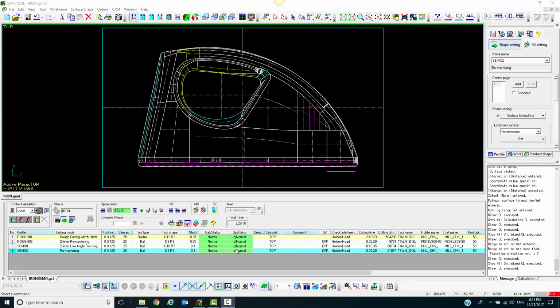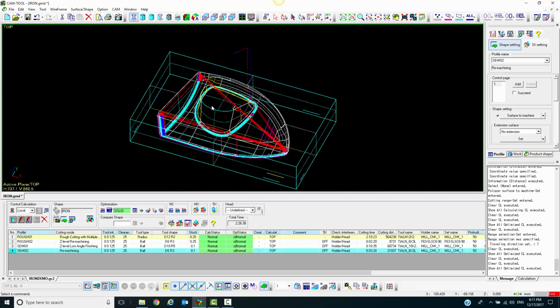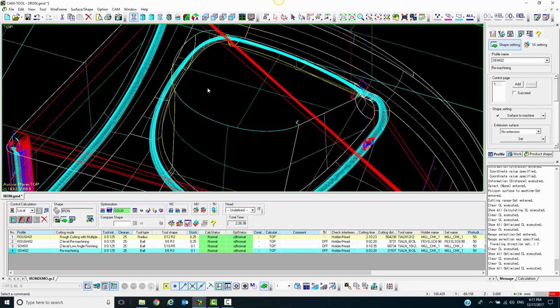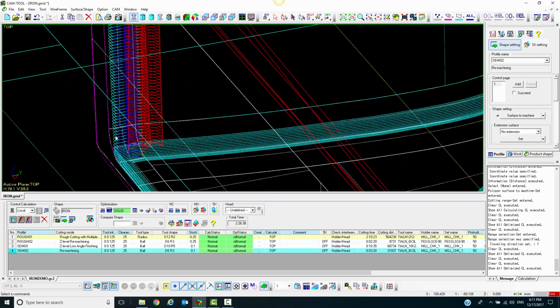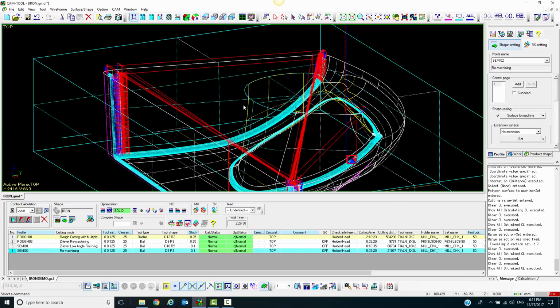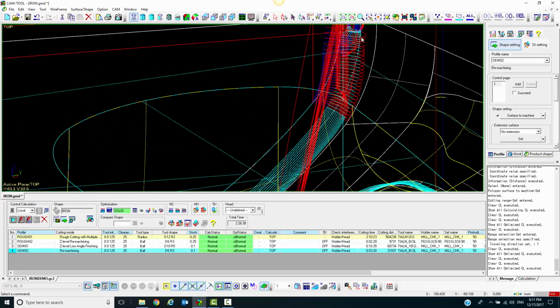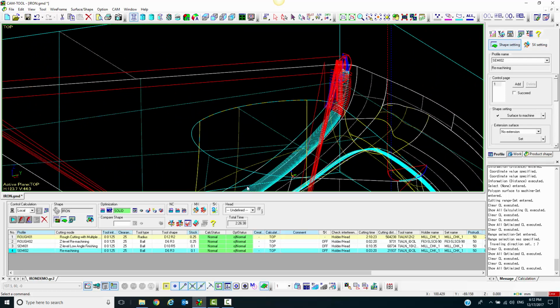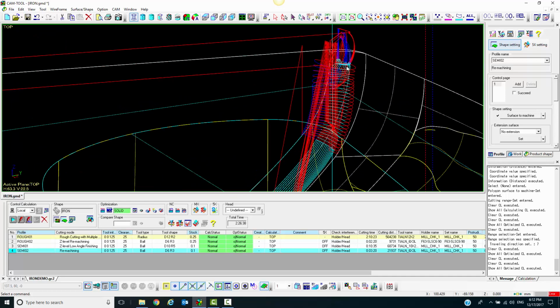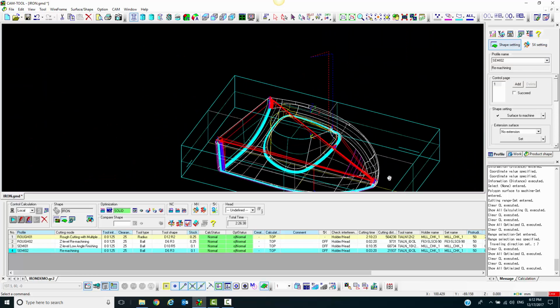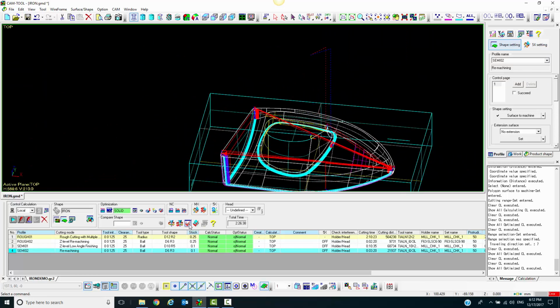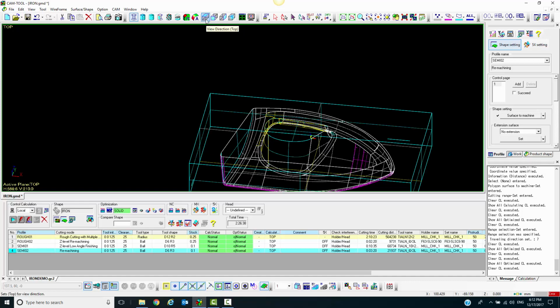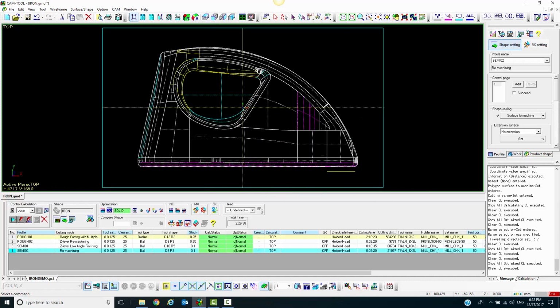Now that our toolpath is optimized, we can double click to have a look. Looking at it, only remachining the areas that are needed. And again, we can see the difference in our judgment angle. Where it goes anything less than 60 degrees, it will follow the contours of the part. And the higher areas, the steeper areas, it's going to do more of a Z-level fashion. Again, we can clear the toolpath, and we're ready to move on to the next toolpath.